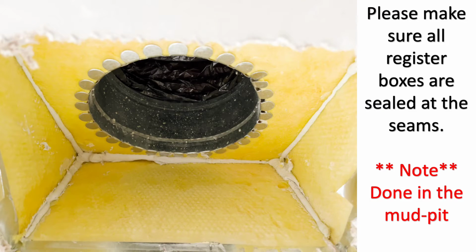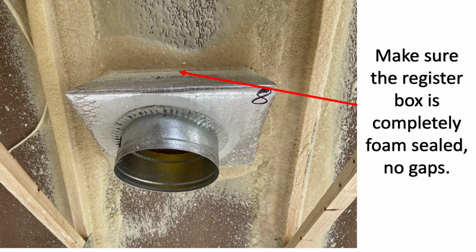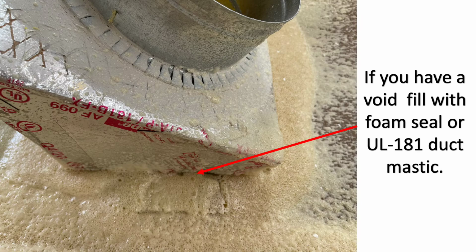Please make sure that all register boxes are sealed at the seams. Note, done in the mud pit. Make sure the register box is completely foam sealed, no gaps. If you have a void, fill it with foam seal or UL 181 duct mastic.